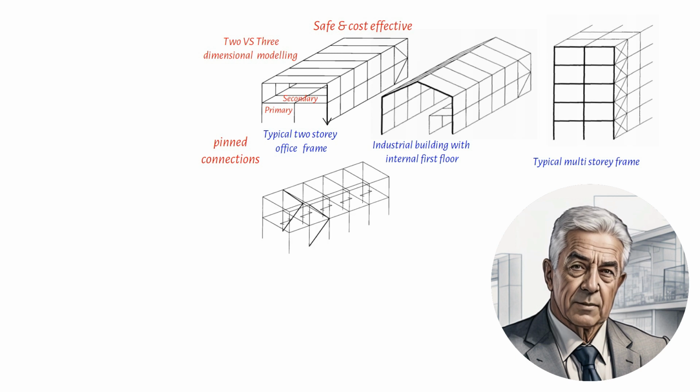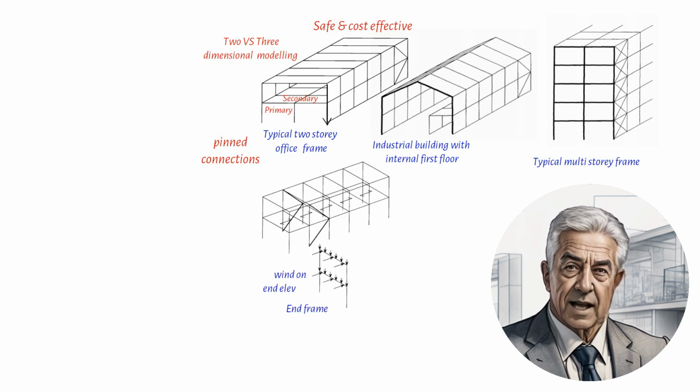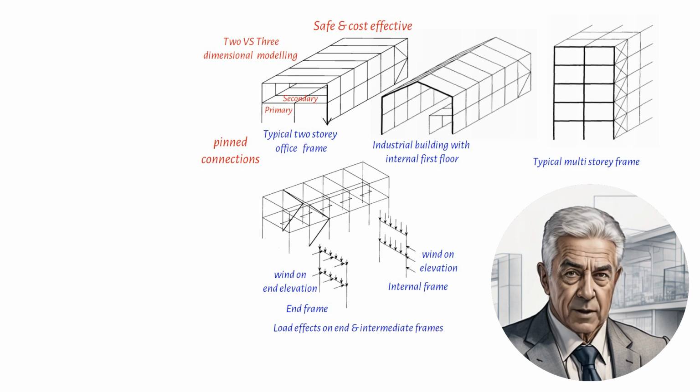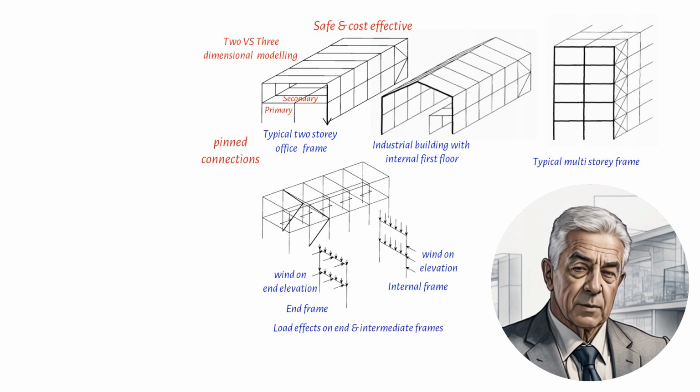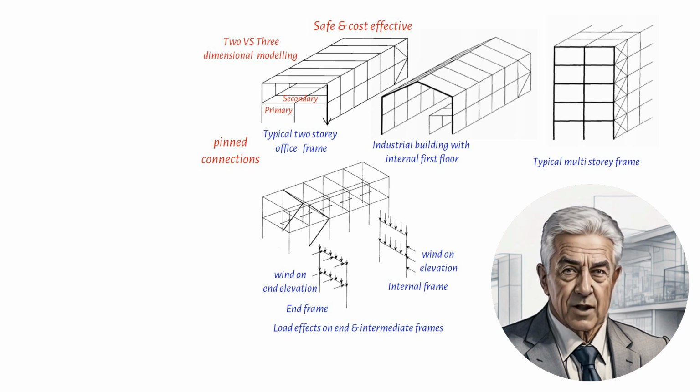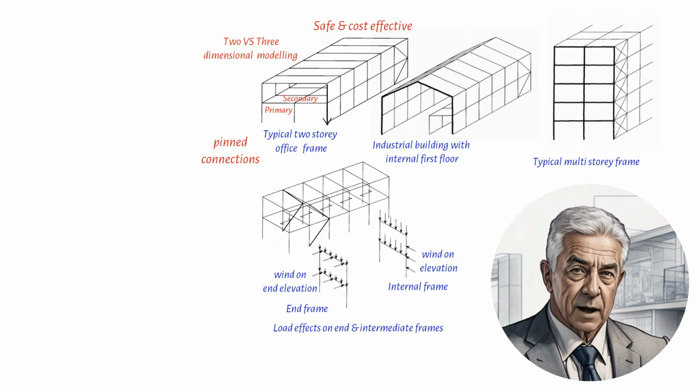Moving on to modeling, two-dimensional models have several advantages, including simplicity in analysis and output, greater rationalization in member and connection design, and practical benefits during fabrication. Therefore, a two-dimensional frame with simple ties in the other plane is recommended for economical fabrication.